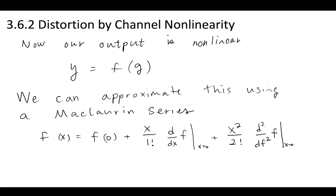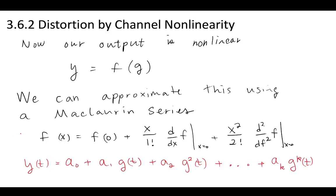We can model this nonlinear output using something that's pretty common for engineers, a Maclaurin series, which is a special case of the Taylor series. The Maclaurin series has a chain of derivatives that we can use to approximate the function. So we'll consider our output y(t) modeled as a Maclaurin series, and our input, remember, was this g(t) function.